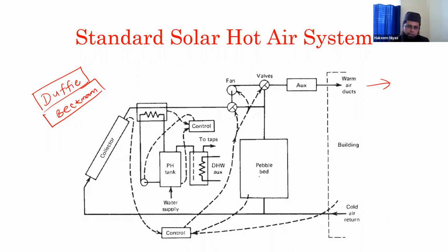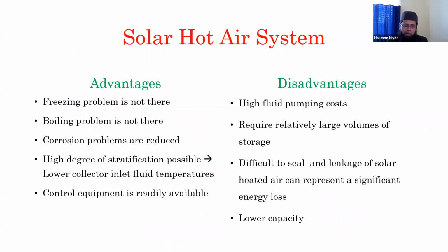The pebble bed is nothing but a storage system. If there is no requirement of warm air during the day, it can be stored in the pebble bed storage system and used at night. There are many advantages here: no freezing problem, no boiling problem, no corrosion problem.